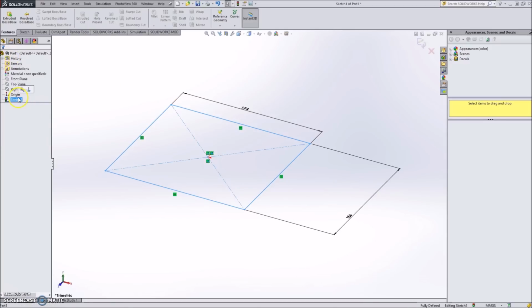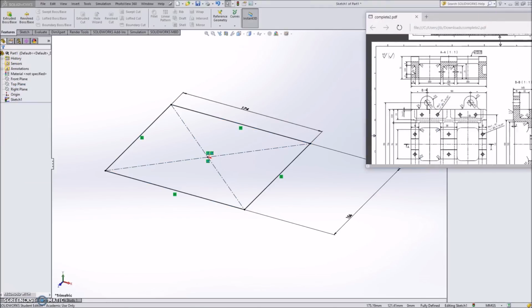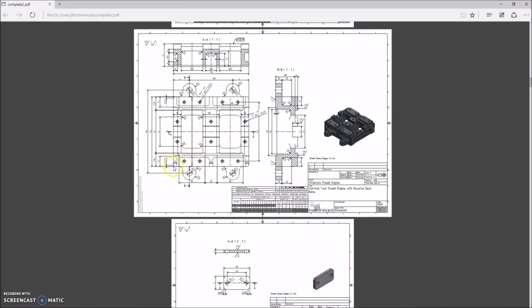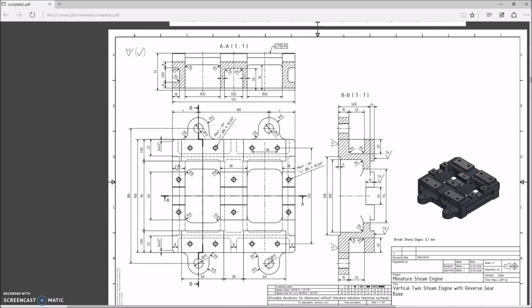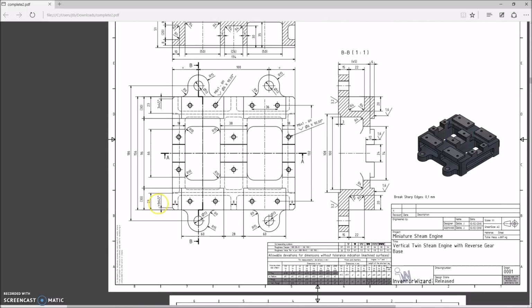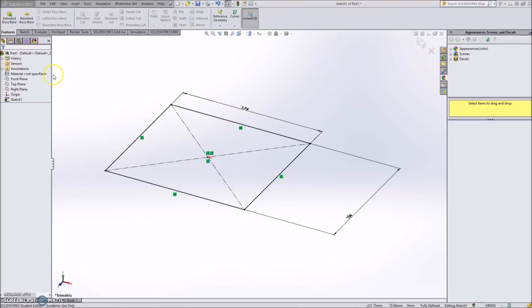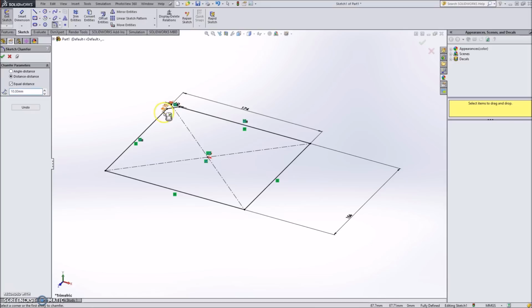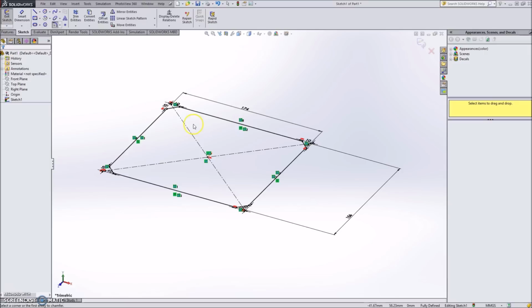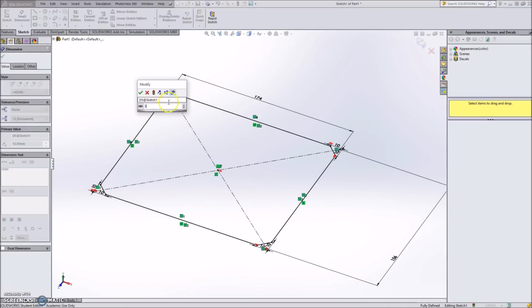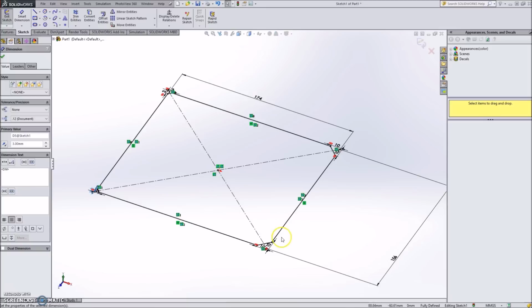And actually, first, let's go back to that sketch. Notice that we have some chamfers along the edges here in this part. So we're going to go ahead and do those chamfers in the sketch. We notice those are 3 millimeters deep by 45 degrees. So if we come to sketch, sketch chamfer, and we select these 4 edges, change this to 3 millimeters, and oh well, it did not change all of these. Let's just go through and change each of these to 3 millimeters.